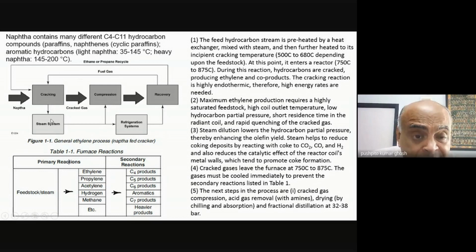Now, the other thing that you have to do is that's not all. Even with all that, it's great, you can control it, but you need to rapidly cool it. So imagine you're heating it at a high temperature, it's cracked, and then you rapidly cool it down. That's how they are able to arrest the formation of all these secondary reactions. They will always take place. It's a question of to what extent.